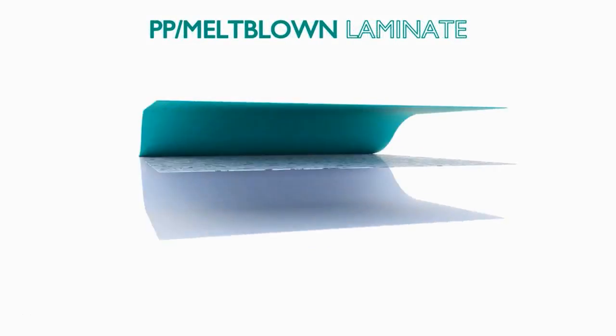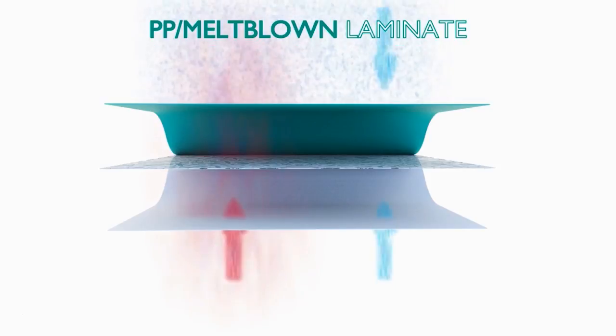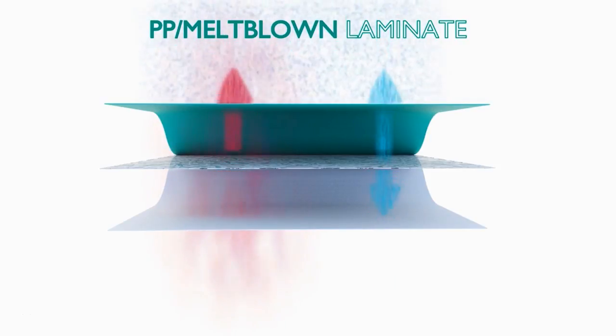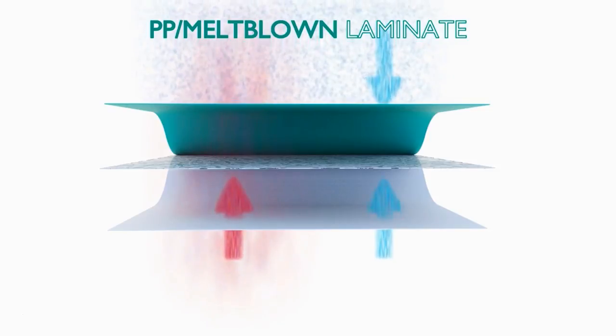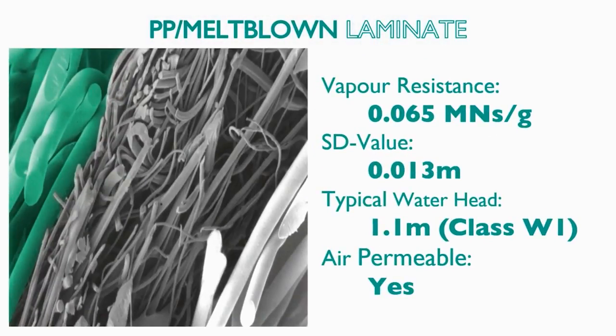Polypropylene membranes with a melt-blown core, such as our roof shield, replace the microperforated Phelim core with a layer of microporous fibres. This comprises a matrix of fibres many times smaller than the human hair, which allows the smaller water vapour molecules to pass through, while larger water molecules are blocked. Membranes with a melt-blown layer offer a higher permeability to water vapour, further boosted by air permeability, which provides actual air changes through the loft space. This comes at the expense of a slightly reduced waterhead compared to other membrane types. However, as the membrane still meets the requirement specification for W1 water tightness standard, this is of little importance.